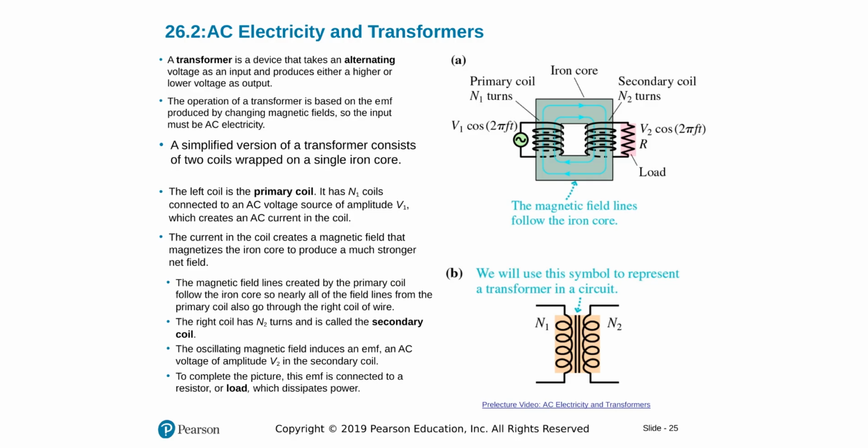So I want to talk about transformers a little bit. They are very useful in changing potential. We feed a potential on one side, and we can take out another potential to our desire and use it for a device that we are using. It works with alternating current, which is why we want to use alternating current in our homes. How it works is that we have a loop of wire on one side, an iron core, and a loop of wire on the other side.